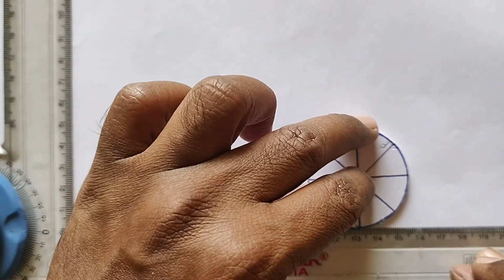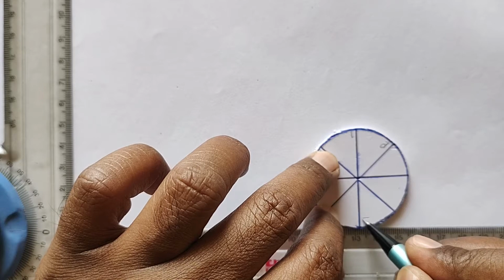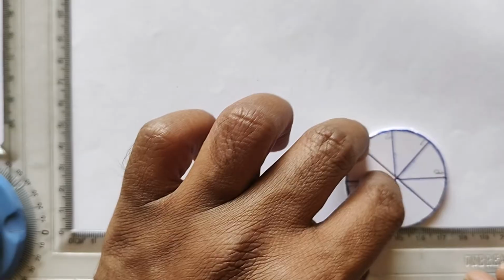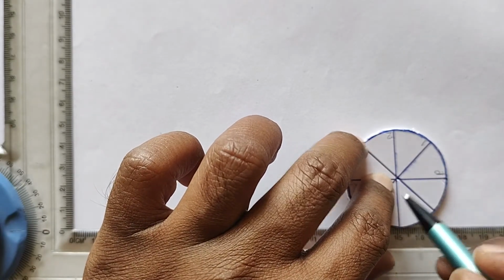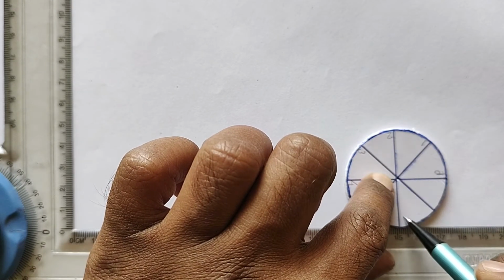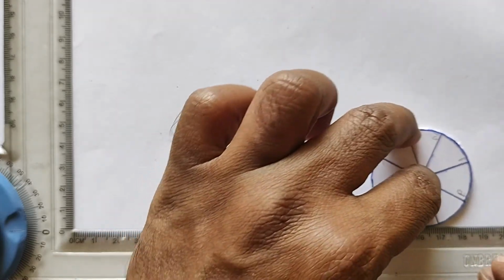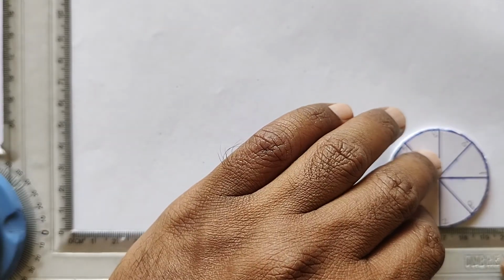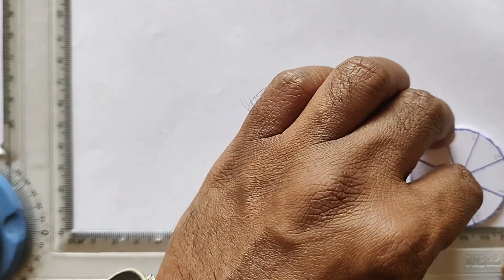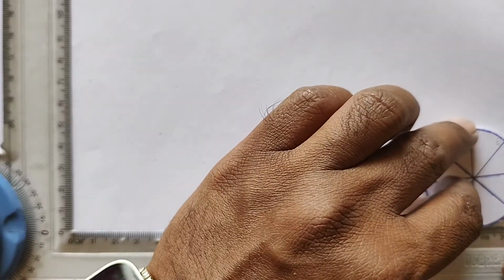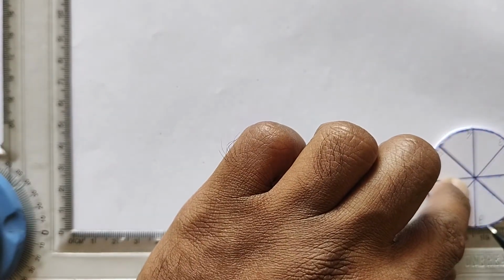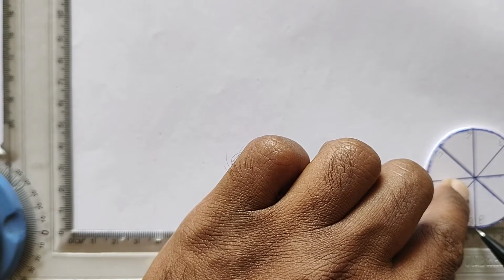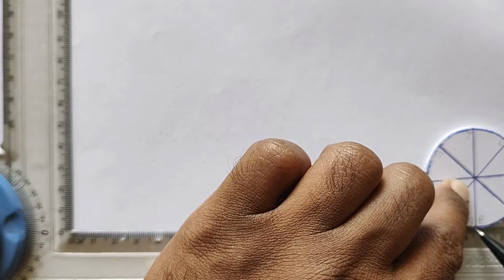then 5. So like this the disc or circle is rolling, and the initial P point which is given at the contact, its location is varying. This is 6. When it reaches point 7, P point will be here, and when it completes one circle rotation, it will cover exactly the circumferential distance and reach 8. That means again P point will be at the contact of line and circle.